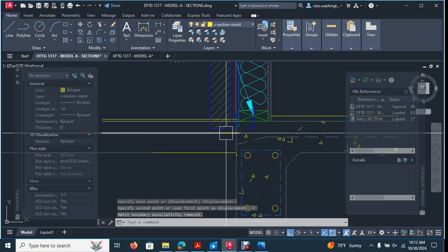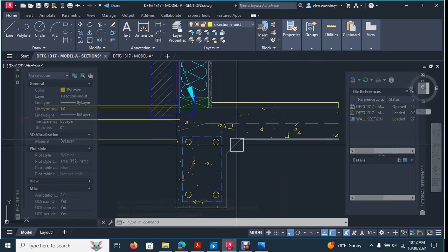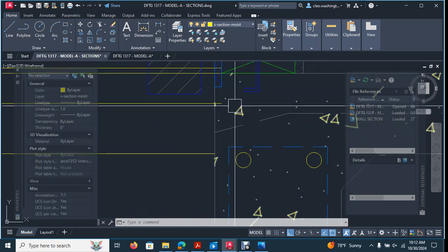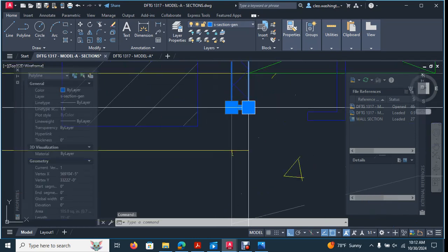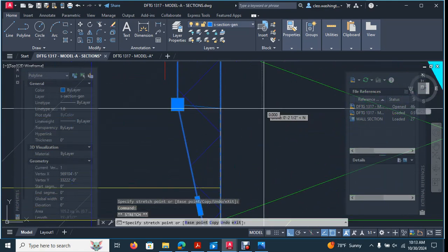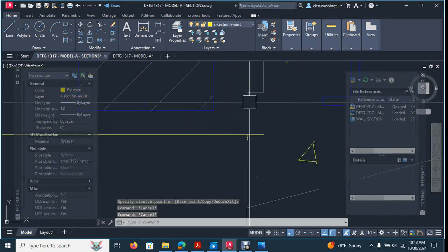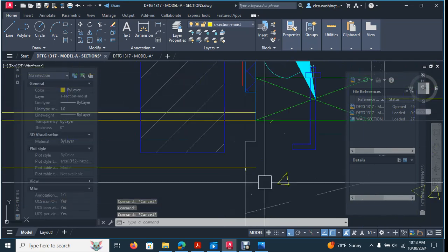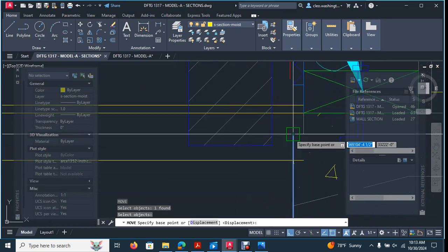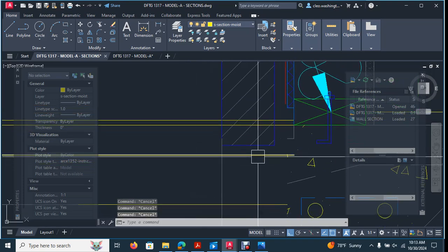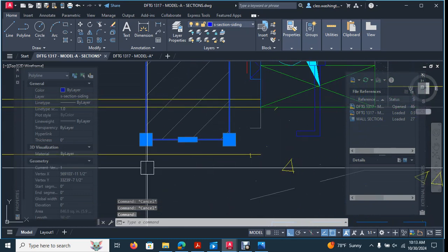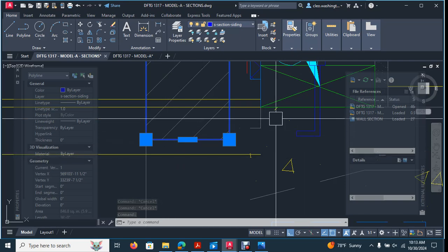All right. And now let's make our modification to our slab edge condition right here. So essentially what you would have is, this is your sheathing. All right, let's go ahead and take that line and raise it up some. Doesn't have to be perfect, but just raise it up because this is what we want to modify, is this right here. All right. So we need to take this line and move it all the way out to the edge of the brick. Okay. Now we need to actually take the brick, because what's happening is the dap out here, this L right here is called a dap out.